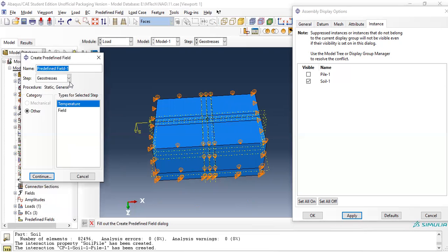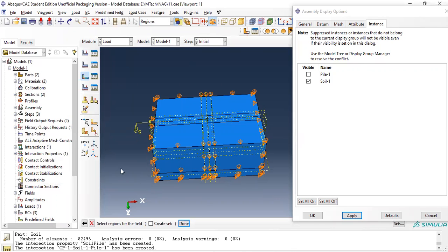That is the vertical stress due to the self weight of soil body. The ground surface will experience some vertical stress, gamma into z. At the top, z equal to 0, so gamma z equal to 0. At the bottom, some z value will be there, so gamma z value will be there. Go from the initial stage, mechanical to static stage. Continue.